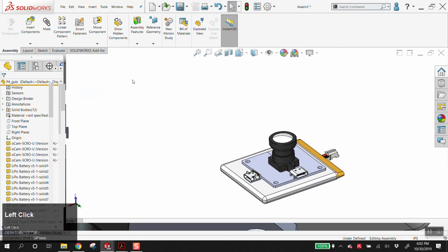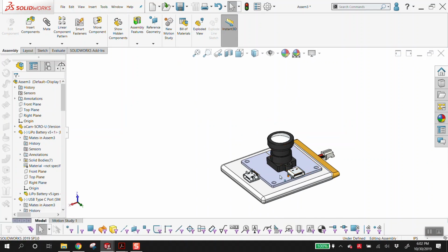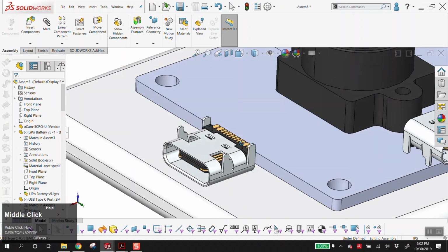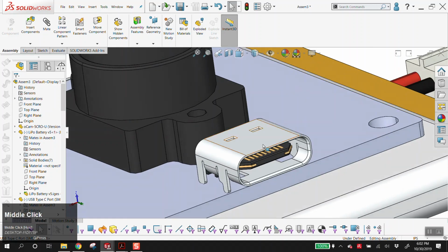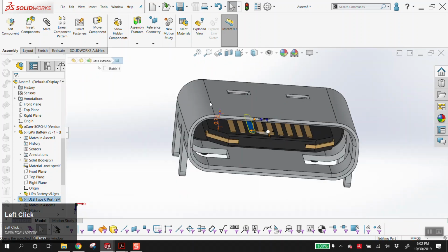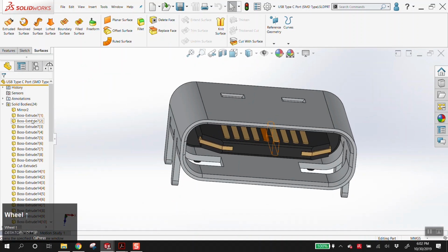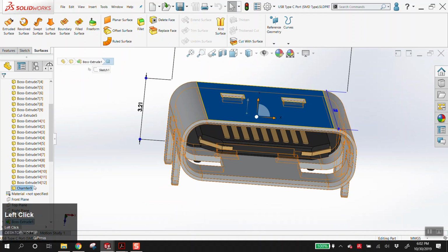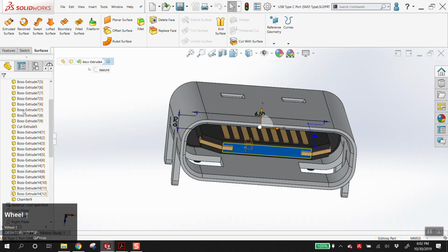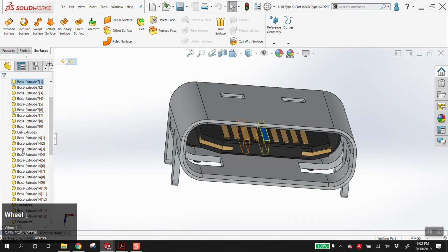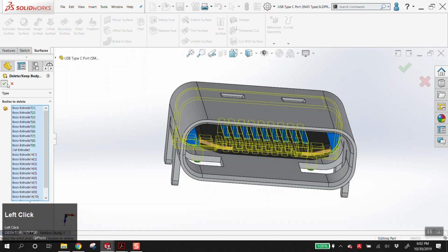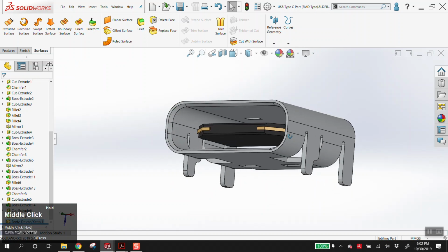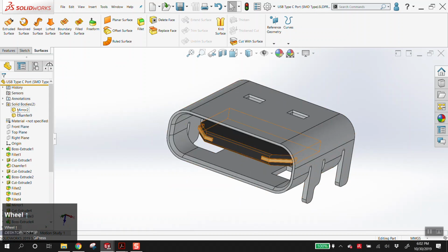In retrospect, being aware of this, what I would have done and what I would recommend you all do is go back to our assembly here before you save it out as a part file. If we open up this component here, if you look at what's visible, we have the chamfer and we have the mirror. If we put in a delete body command here, we've now simplified this to basically two bodies.